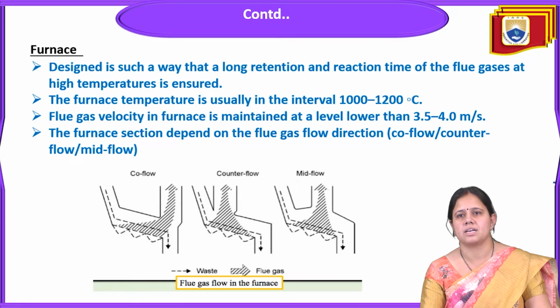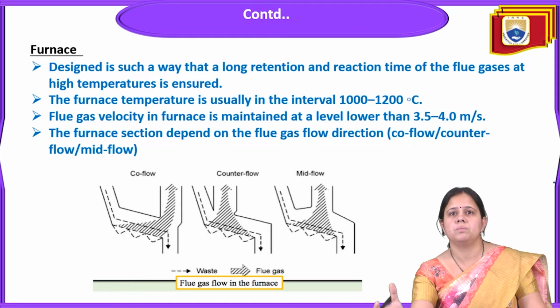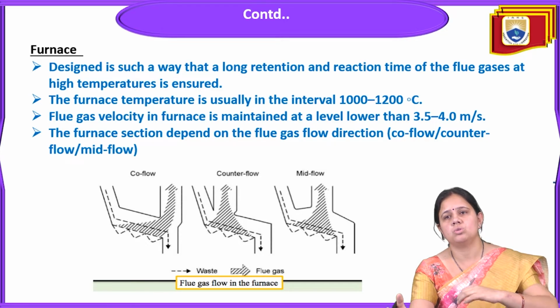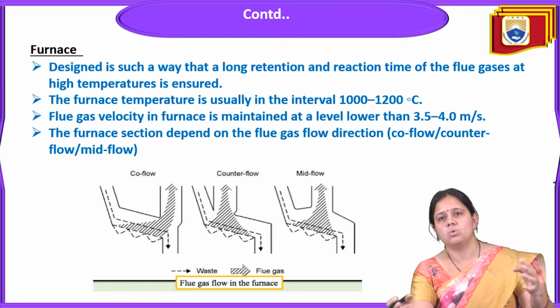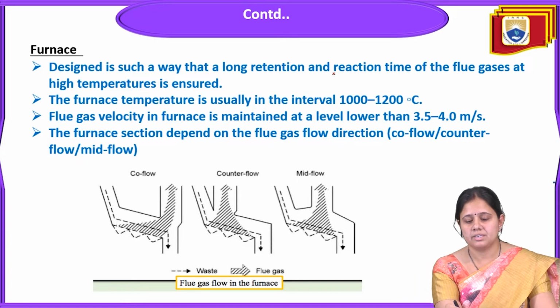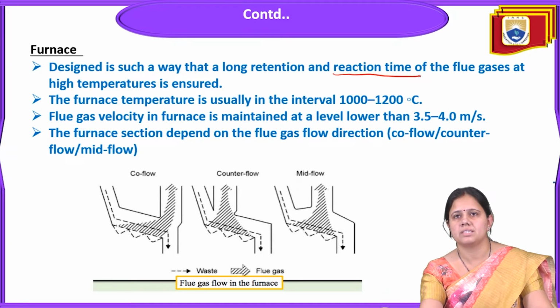Next is the furnace design. How should the furnace be designed? The furnace is the main thing, because the flue gas will flow through the furnace only, and the whole combustion process will take place inside the furnace. So the furnace should be designed in such a way that a long retention and reaction time of the flue gases at high temperature is ensured.